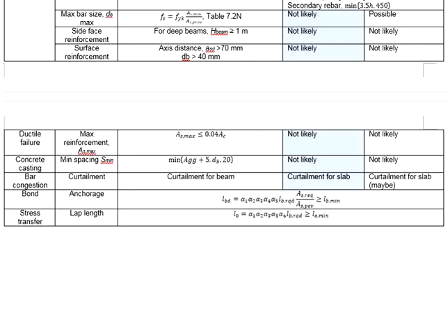design approach. One of the noticeable differences between the Eurocode and the British standard is the methods to determine the anchorage length and the lap length. In fact, Eurocode is more powerful in this aspect, because the calculation of the required length has been identified and discriminated by the regions where the lapping length is required, whether it is at the good bond regions or the poor bond regions.